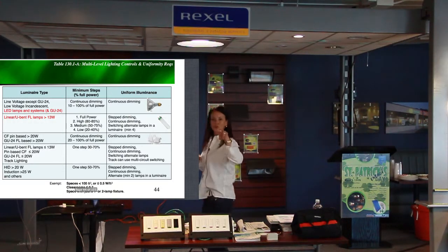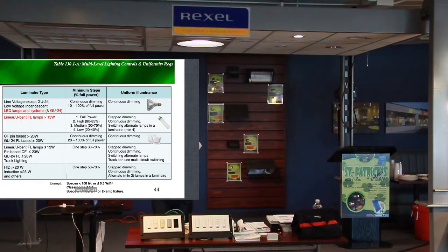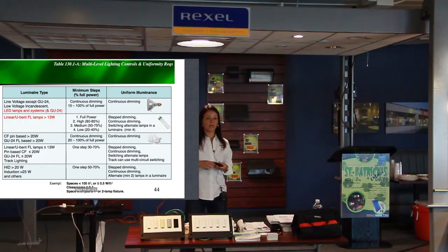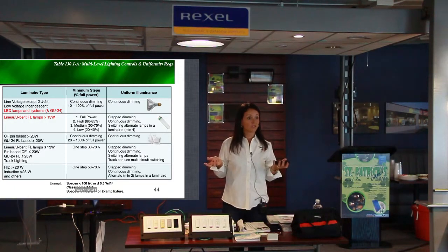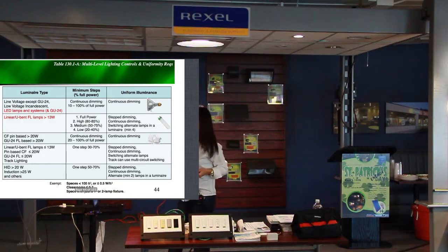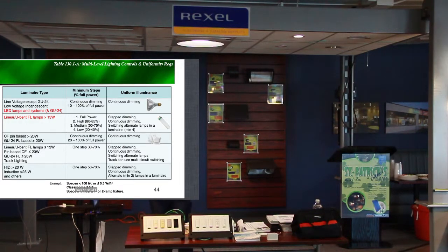Before, we were able to do 2 lamp luminaires, right? A, B. So I have 33%, 66%. Actually, with the 2 lamp, I would have 50%, 100%, and 0. With the 3 lamp, I would be able to do both. It's impossible to accomplish that with a 3 lamp fixture now, or a 2 lamp fixture, unless you have a dimming ballast. So low, 20 to 40 percent with a 3 lamp fixture, I can do it. Medium, 50%, pretty easy. The high level, between 80 and 85%.